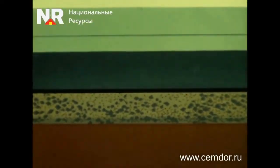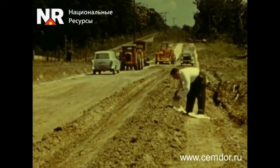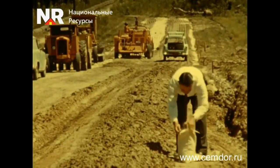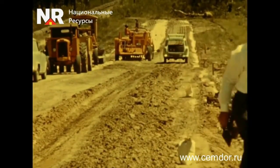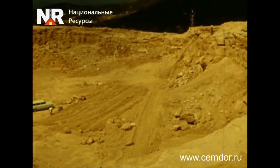Soil cement is a semi-rigid material having a high compressive strength limit. It can withstand significant axial loads without deformation. At the same time, having a high flexural strength, it resists dynamic loads from moving vehicles well. To determine the suitability of the soil for constructing the structural layer, samples are taken from the road's right-of-way at regular intervals along the road under construction. When using imported soil and a special soil quarry, it is also necessary to systematically analyze the samples.